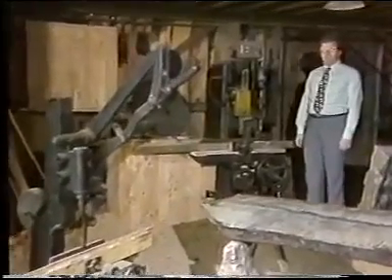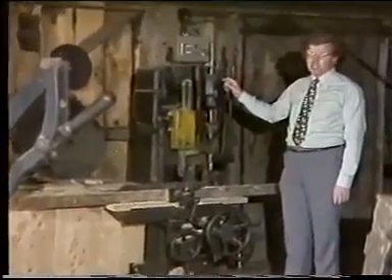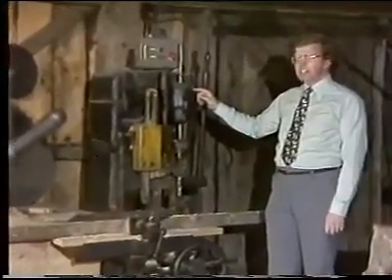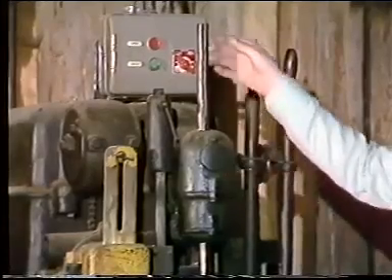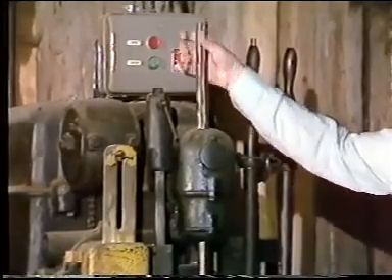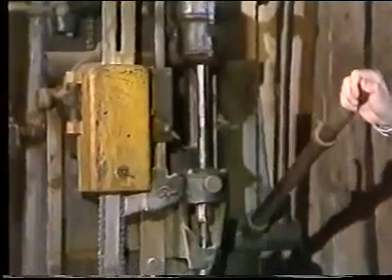We've got an example of another kind of joint on this drilling machine that dates from about the turn of the century. The joint is a cylindric pair, and the links are the body of the drill here and the shaft, which both rotates and has an independent translational motion.